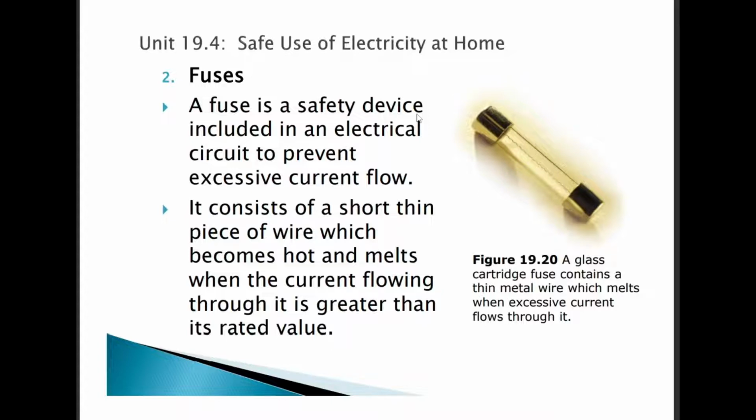Now, a fuse is just a piece of electrical wire connected between two terminals. I have deliberately designed it to be a wire. Why? Because wires have low resistance. So what I'm expecting is that the moment the current exceeds a certain value, this piece of wire will heat up so much that it will eventually melt and sacrifice itself to protect the rest of the circuit. Do we understand how the fuses are doing this job? Right? So this is just a piece of wire. They are sacrificing themselves. They will themselves become heated up.